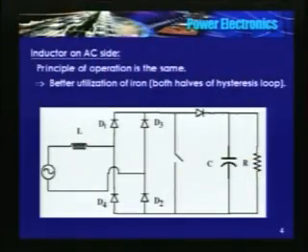So when I close the switch, in the positive half, you have D1 conducting and the switch, D2 conducting. When I open the switch, the inductor current flows through D1, diode DB, load and D2 back in the positive half.